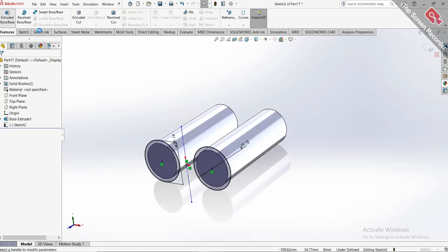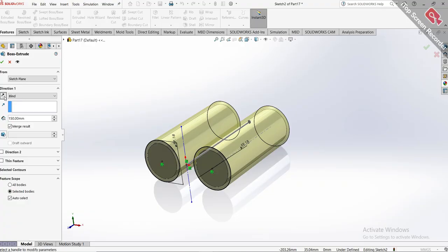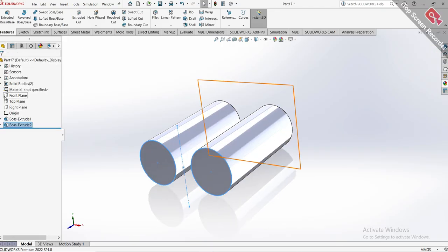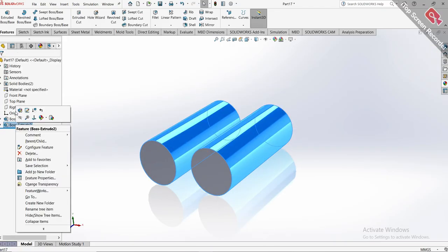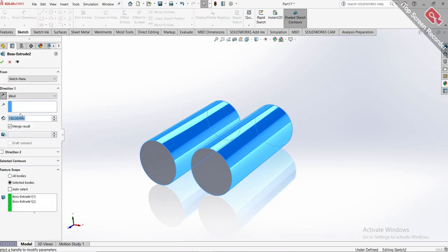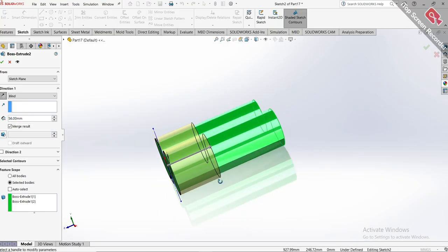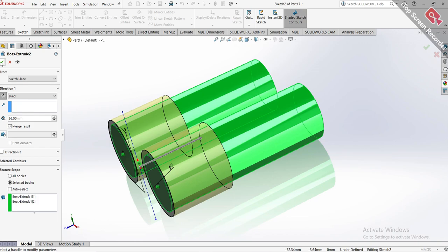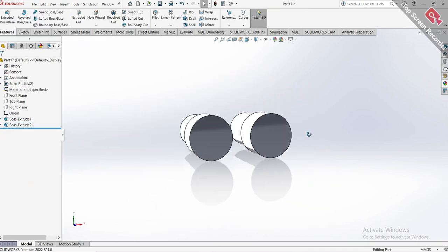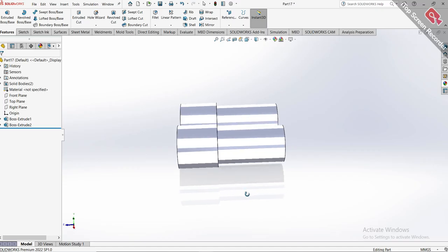Click on extrude boss. I'll click this portion to reverse it. I'll make it 56. Oh, not like that. I click here, edit feature, come here, say 56. So it's up to this length, it's going to get to this length. I'll click okay. So I've been able to get this front. Then the next thing I'll have to do is the circle.